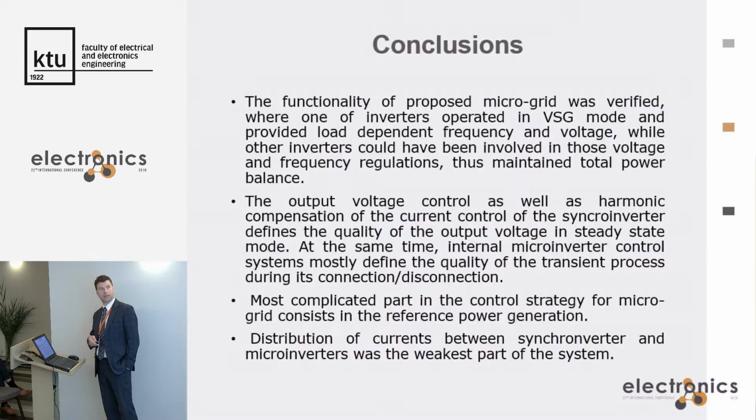Okay, very shortly, that's all about the simulation results, and the main conclusions are: the functionality of the proposed microgrid was verified, where one of the inverters operated in virtual synchronous generator mode, and other inverters could be involved in voltage and frequency regulation, thus maintaining total power balance.